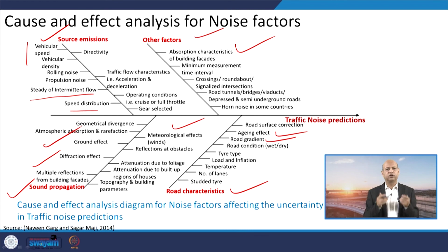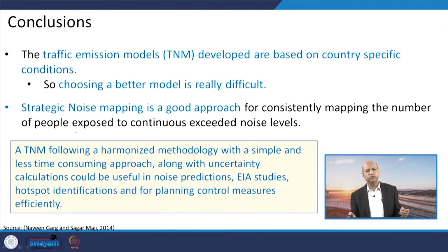All these factors participate in a cumulative way in how much noise will be produced, and that way we should take them into account in those empirical relationships, so that our model based estimations or predictions are nearer to the real noise level. Otherwise, if the estimated noise levels at the receptor are erroneous and more than actual, you may design barriers much more than required, so a lot of money will be wasted. If it is under predicted, then the noise barrier you design based on that value may be underperforming, and even with a barrier, we can have more noise at the receptor.